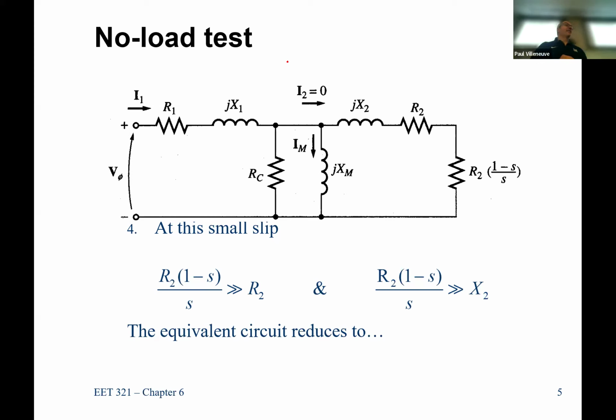Got it. Inductor shorts out over DC, right? So this just goes to be a short circuit, as does that. But you all were saying sort of the same thing, like what's happening with the AC. The AC is giving you that changing magnetic field, which allows that inductor to actually be an inductor. But DC over time to an inductor, the inductor just shorts out. So the only thing you're going to get is R1. You won't get R sub C or R2 in your final circuit when you do the DC test.